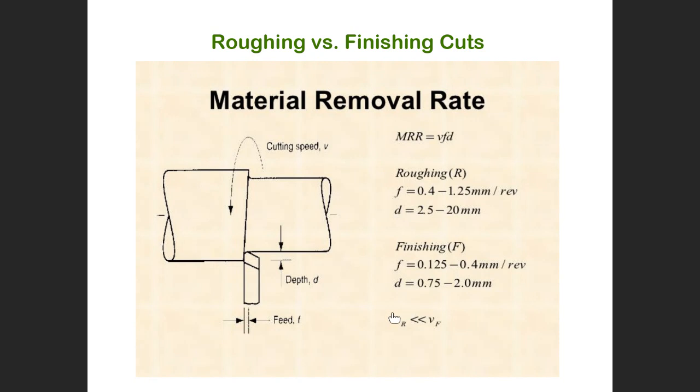The rotational speed in rough cutting is smaller than in finishing. In finishing we have very high speed. In rough cutting, we usually reduce the speed. Right? Did you get it? Did you get the difference between rough cutting and finishing? So usually we start with several rough cuts and then follow with one finishing process. Right.